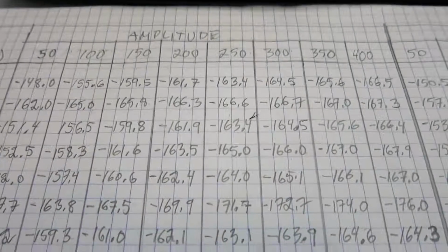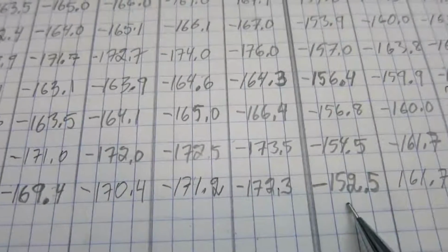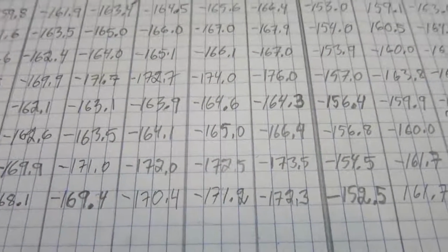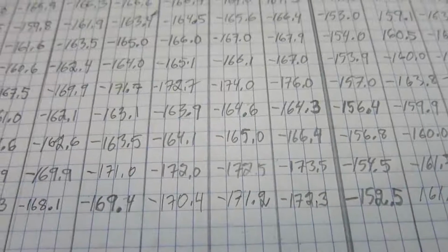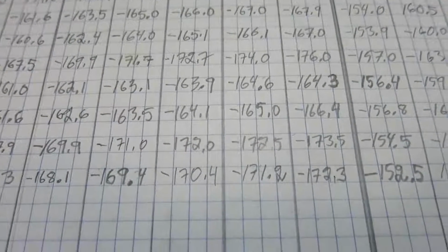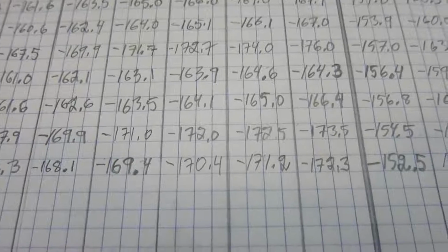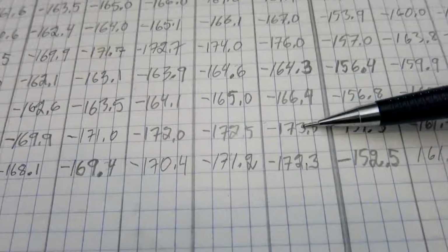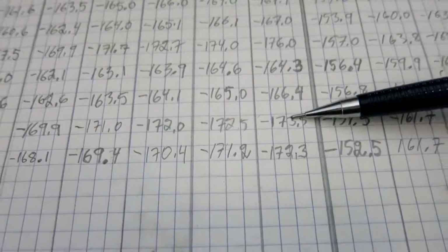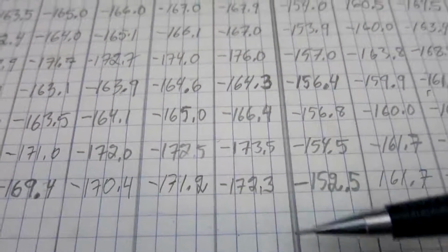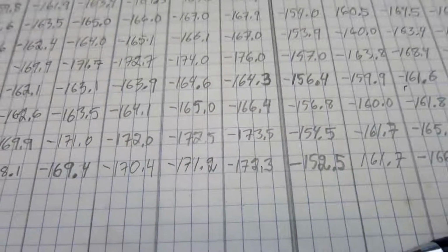Here is 300 Hz, and about 1 dB here. And I should expect an improvement rather than a degradation. I think perhaps that the amplifier uses positive feedback, and feeding it with the output of itself, which should be minus 173, that should give a better result than feeding it from the Wenzel, which was 167. But it works the other way. So this is probably because of positive feedback.